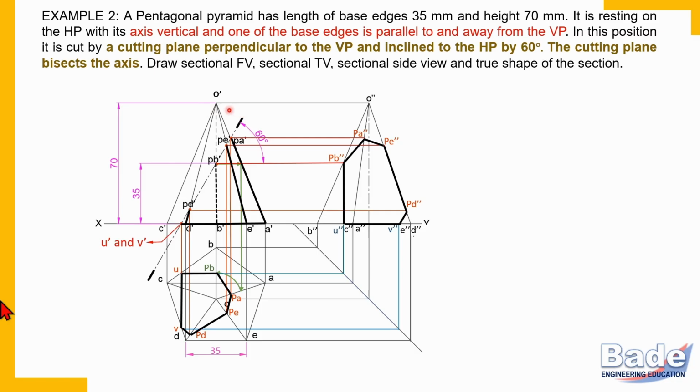Now take help of this diagram of this view and identify the retained portion in the top view. Now check here, points UV. The left side of UV is removed, so the left side of the section is removed. So this portion is removed. Don't make it dark. The right side portion of UV is retained, so the right side portion of the section you should make dark.